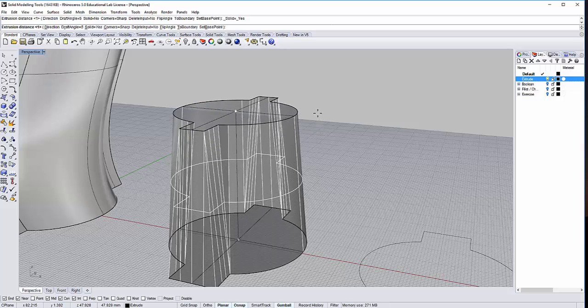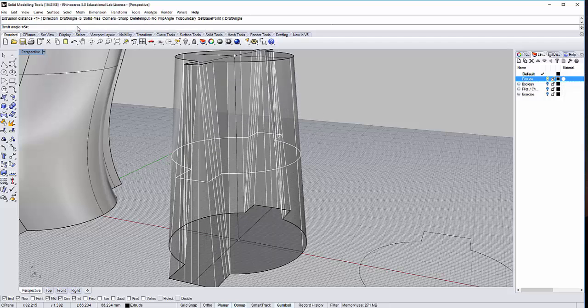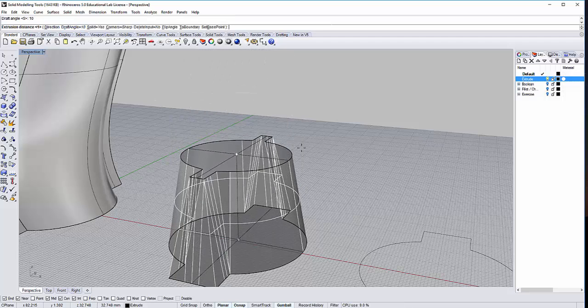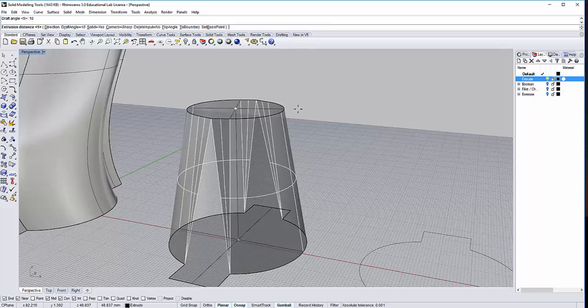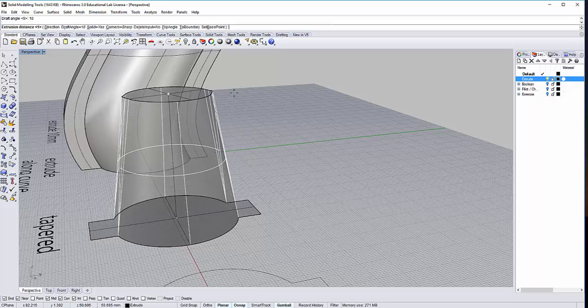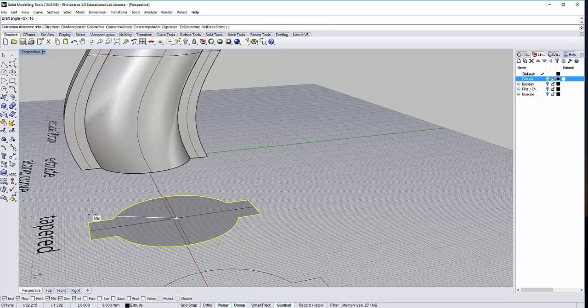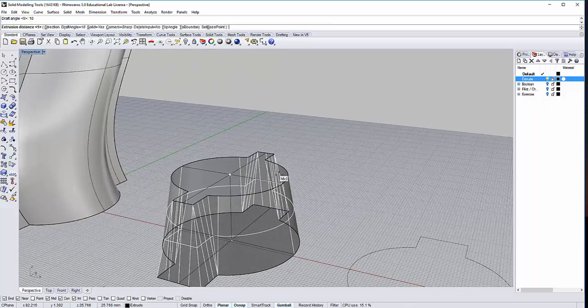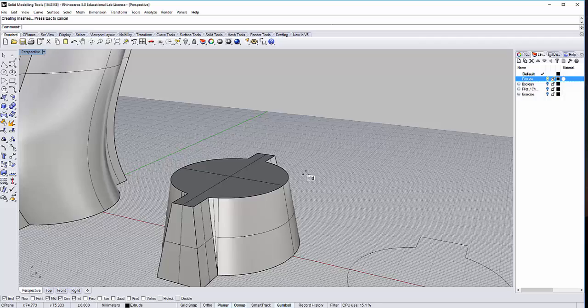Alright. So the tapering angle you can adjust. Let's say for example here I want a much more higher. Notice how sharp it becomes. Right? But you cannot go too far out. Why? If not, the Rhino cannot register, let's say for example, the material here. So I would recommend somewhere along this line.